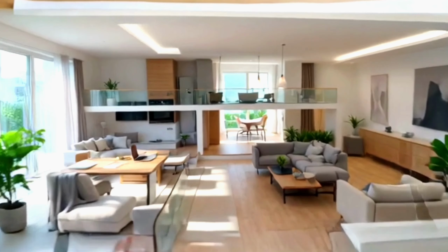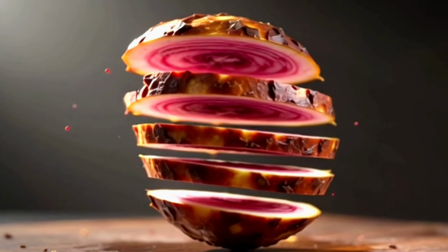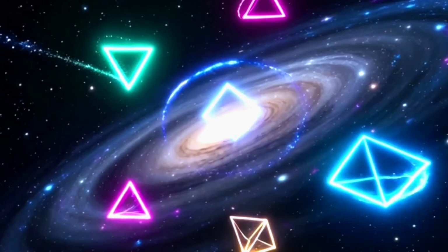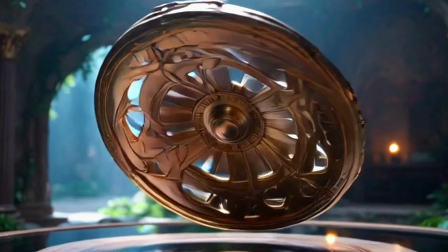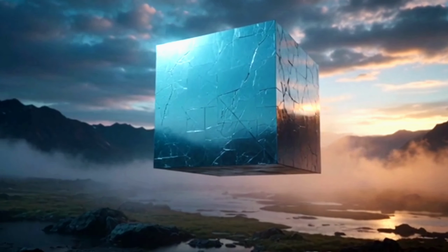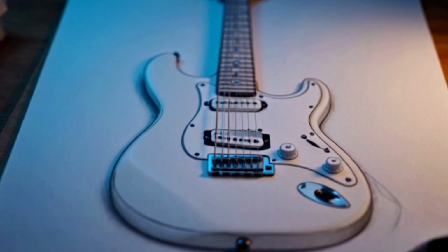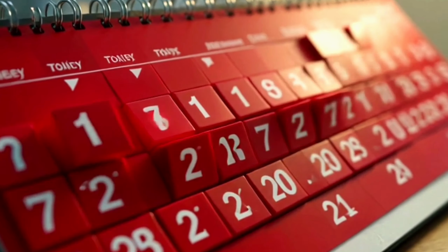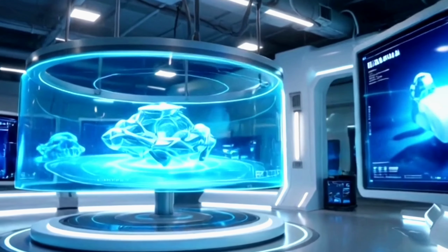Let's look at the key dimensions. The object has a total length of 75 mm, a total width of 50 mm, and a total height of 50 mm. There is also a semicircular profile on one end, a cylindrical hole of diameter 12 mm, a central rib with thickness 12 mm, and a rectangular slot on the base. Understanding these features first makes the drawing process much easier.